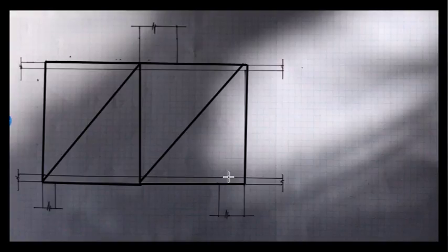But remember, we have reinforcement here. If we design this as a strut and tie method, how are we going to get the bar from here to here? Or similarly, if it was designed to be a deep beam in flexure, how is the reinforcement going to transfer from here to here? Are the two panels going to be able to be connected properly? So we need to understand all the forces that go together to connect the two panels.